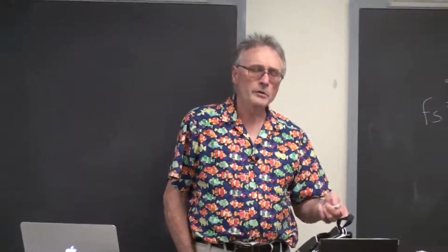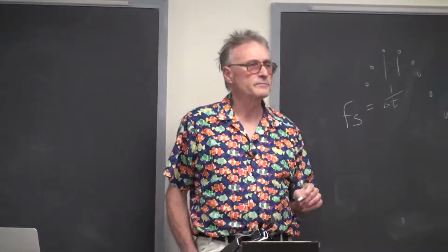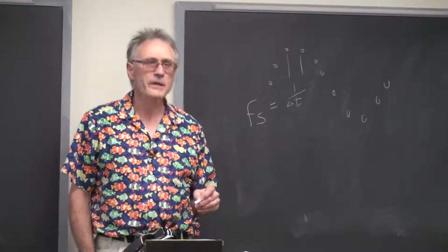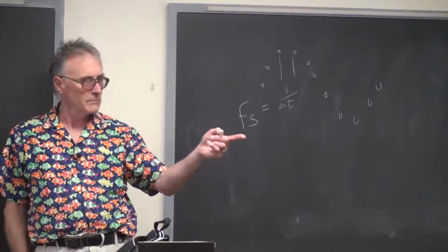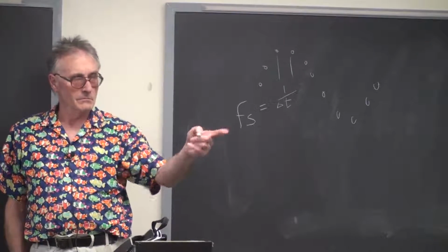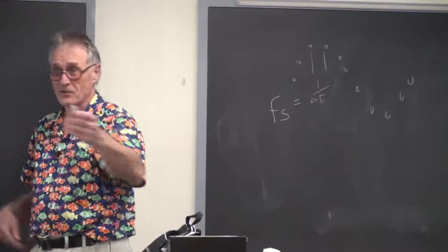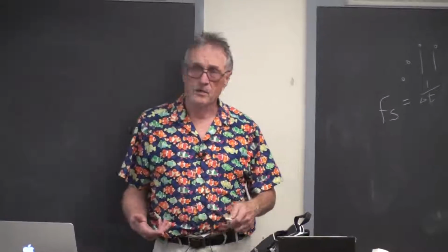But in the code, how are you going to set fs? What's the mechanism for setting the sample frequency? Timer period. Yeah, it'd be the timer period. So the timer period, you're going to set a timer to time out after n cycles.